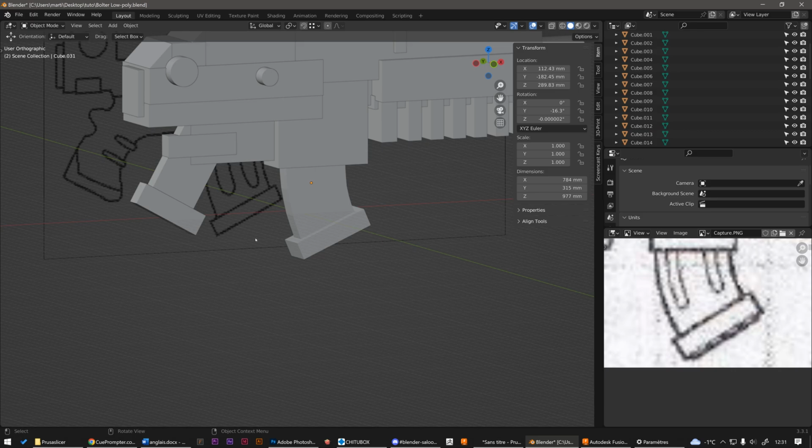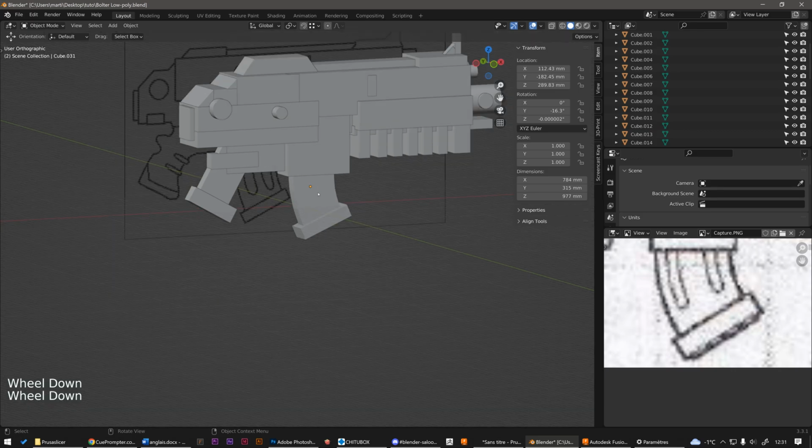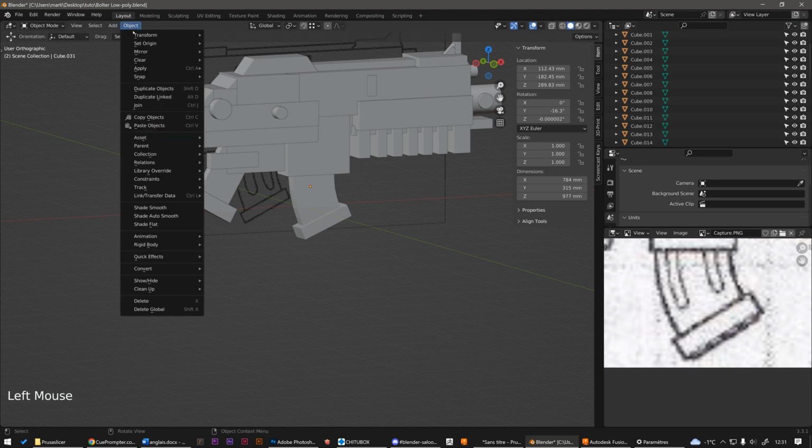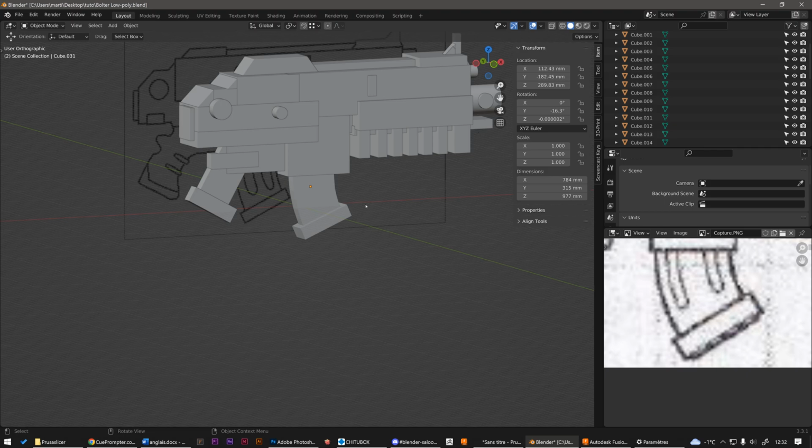So, it was a bit long, but you'll find that most of the time, you won't need to do all that. If you have a non-uniform scale problem when modeling, well, you will apply the scale once and for all. You won't have to do it again later, except if you scale your object again, but it's pretty quick to apply this transformation. Finally, we'll just talk about the normal axis orientation of a face or an edge.